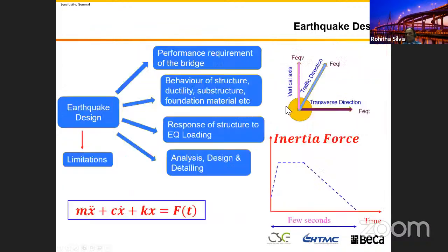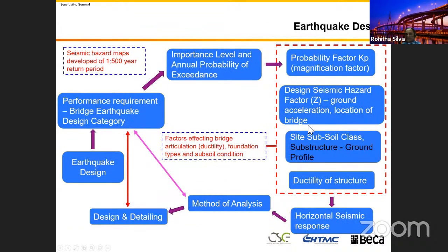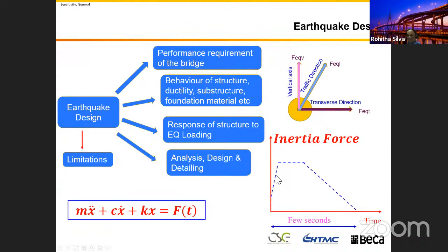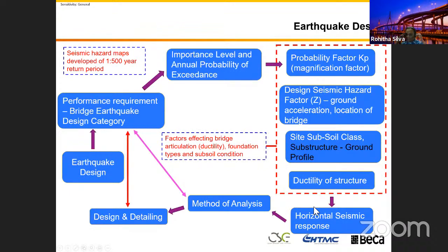That is like this earthquake force with time, because the earthquake is time dependent, then the force you need to develop is a time dependent one. If you know the force, then you can analyze your structure. It doesn't matter, because before all these computers and algorithms came, people still designed bridges for earthquake loading. For example, if you split this into different time zones and apply this force individually, using the principle of superposition, you can still come up with the solution. It's still possible. So we have software to do that now, but you do the analysis.